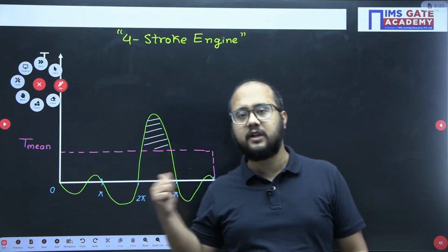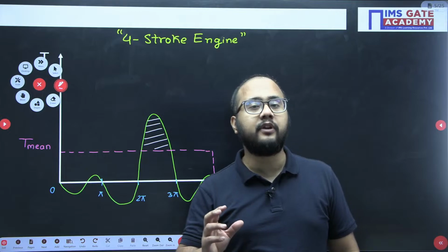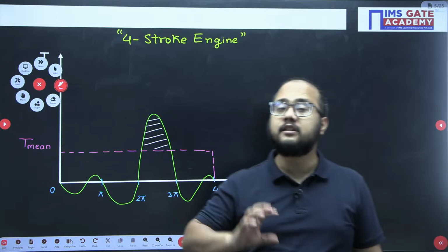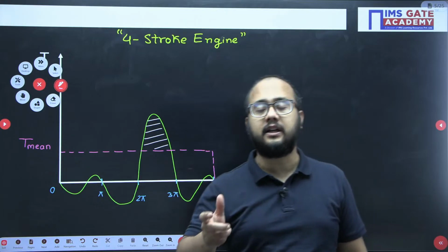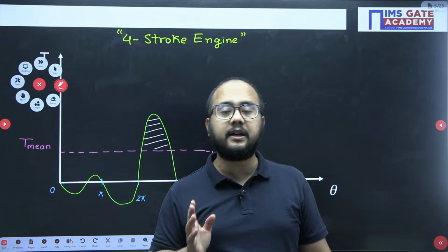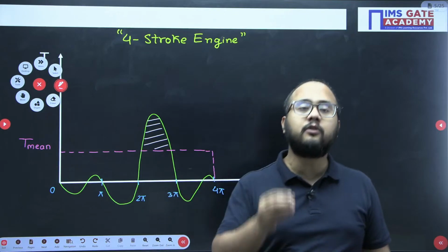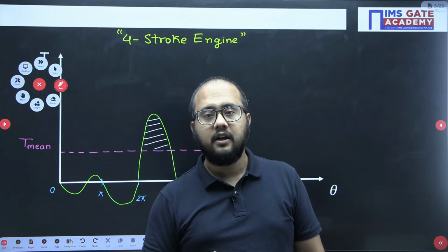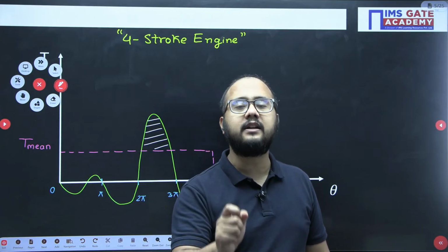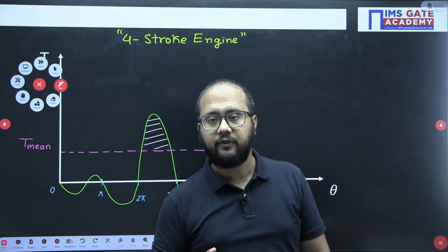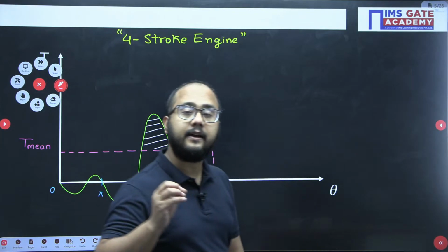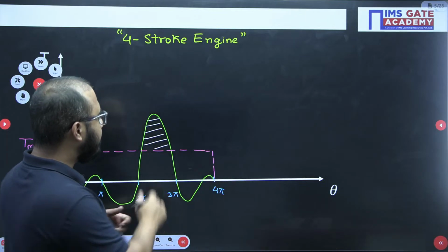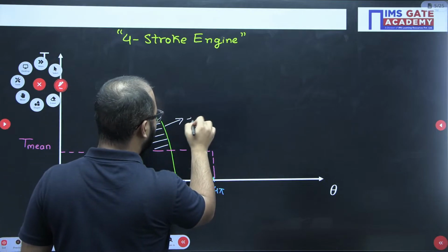Okay, with respect to rotation I am talking here, because for the crankshaft we want rotation. That's why in terms of rotation I am talking. So as high inertia it is having, it is difficult to rotate. But once it started rotating, it is difficult to stop that part also. Difficult to stop the rotation of the crankshaft. So that's why the inertia of a crankshaft is increased by using the flywheel on the crankshaft. Okay, so that's why what happens? The kinetic energy is going to be stored in the flywheel. Which energy? This one, this excess form of energy.